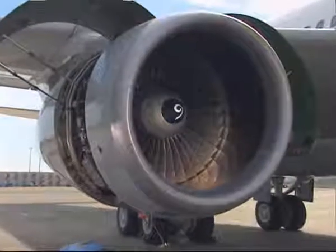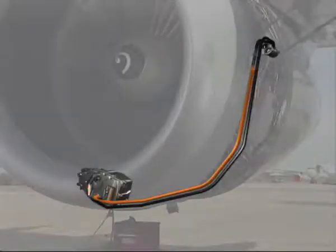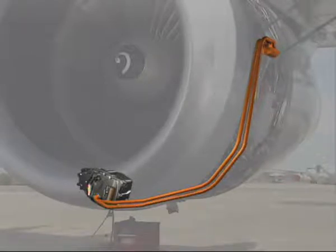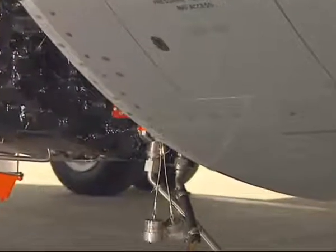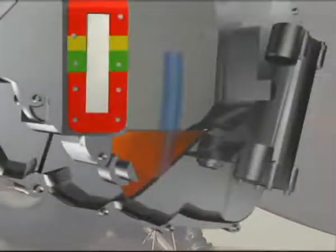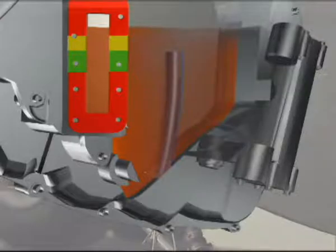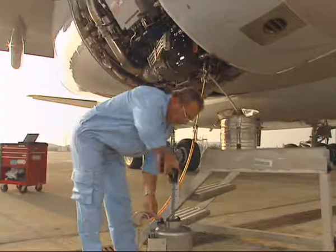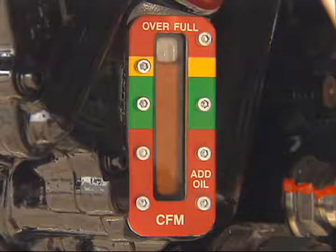During servicing, the oil enters the pressure fill port and crosses the filter, flows through the external circuit and circulates into the cooler, flows through the external circuit and comes back into the IDG case. Keep pumping. The IDG case is then filled with oil. Once the oil level exceeds the top of the overflow standpipe, it flows outside the IDG through the overflow drain port. Keep pumping to fill the entire oil circuit and expel air pockets from the system.